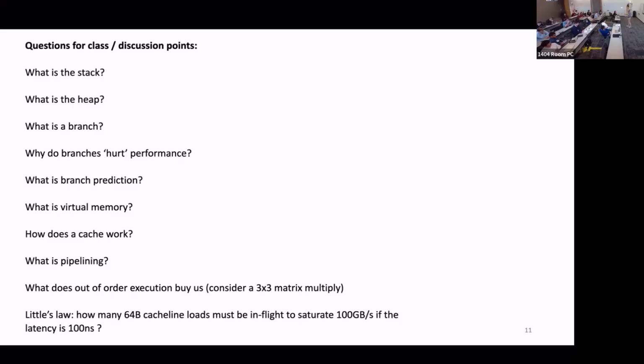So you generate a huge number of registers and a huge number of separate threads of execution that don't have dependencies between each other to generate 150 pending loads. That second solution is essentially what you call a GPU, right? And it's designed around having high levels of memory parallelism exposed to get lots of pending loads and deep queues, and then you can get this kind of mechanism for generating a high sustainable memory bandwidth.